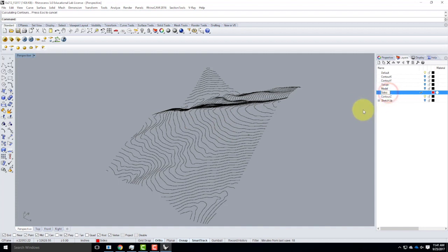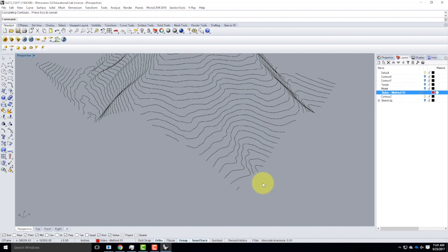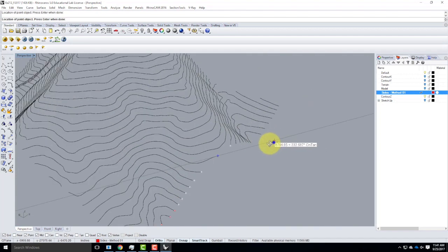Anyway, so the first method of doing this, and actually, you know what? Let me call this sides 01 or sides method 1. And to do sides method 1, I'll do this end, I think. What I'll do is I'm going to come up here to the point tool. It's right here. But I don't want a single point because I have to repeat. I want multiple points. So I'm going to right click instead of left click, and it's going to give me lots of points. And essentially what I'm going to do is I'm going to go through and stick a point on every one of the ends. And assuming that I have endpoint snap on, it should go rather quickly.